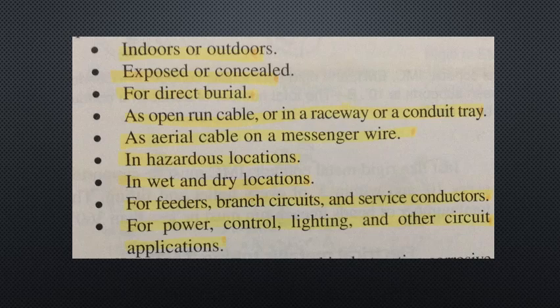Type MC cable cannot be used in destructive corrosive environments, such as buried in concrete or earth that exposes the cable to harmful chemicals and contaminants.